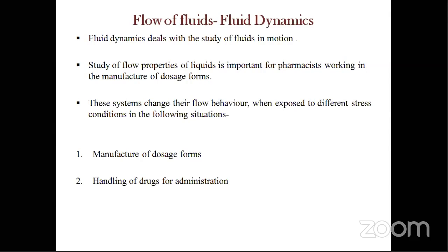When you put them in a transparent pipeline, you see that the glycerin moves faster than the starch paste, because the starch paste is more viscous and stickier than glycerin. So that's why its motion is different depending on viscosity. If your viscosity increases, your flow of fluids or dynamics decreases.